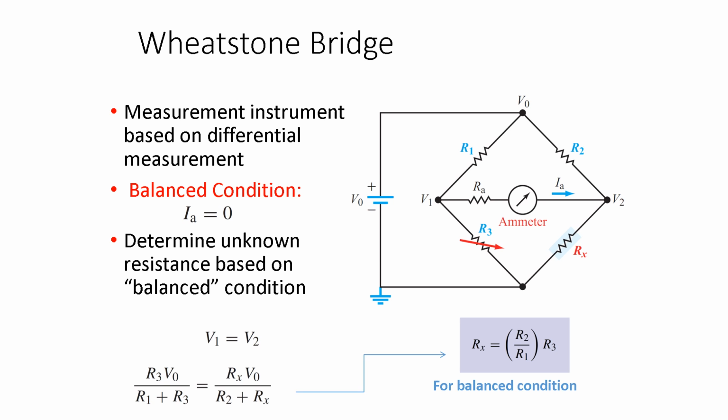And remember, we talked about that by looking at the bands on the resistors and the color coding. So if we have resistors that are 20%, this isn't going to be super accurate. But if you buy higher tolerance resistors that are plus or minus 1%, plus or minus 0.5%, you can start to get some really accurate answers for determining what Rx is.